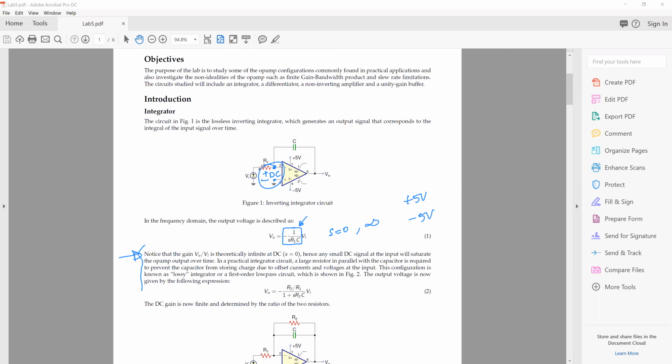And we saw that it's inevitable because practically there is always some error or some kind of offset voltage there, right? So however small it is, it could be 1 millivolt or even smaller, but the gain is so large that it will always saturate. So even before we actually try to apply our inputs, the output is already saturated, correct?